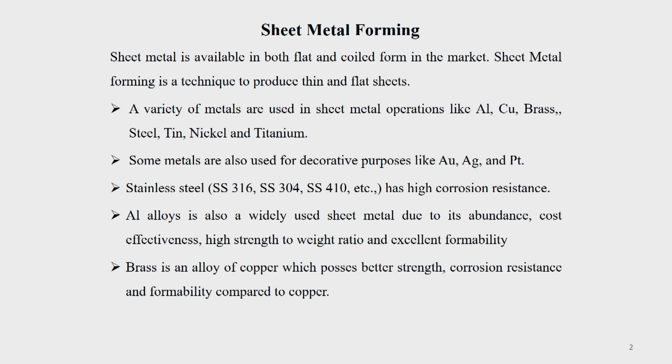Stainless steels are used even in household and domestic purposes, like domestic vessels, glasses, plates. You will find a variety of things. Most domestic applications generally use 316 or 304 grades, but there are other martensitic stainless steels also.